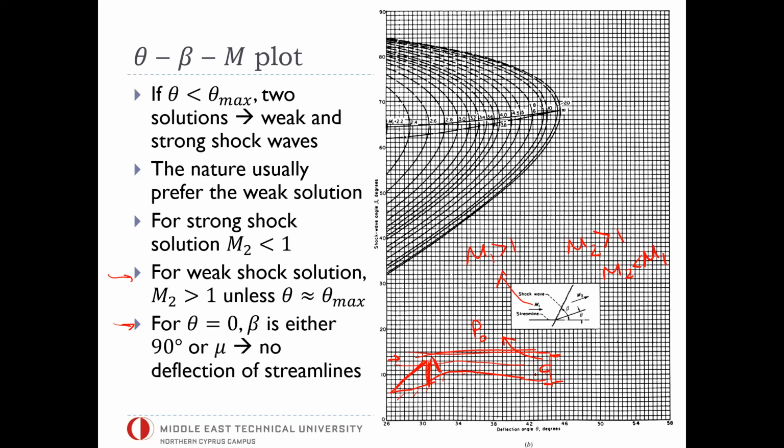So this inlet stagnation pressure is an important parameter in terms of engine performance as well. Therefore, we make use of the fact that we can generate many weak shocks, a train or series of weak shocks, and then maybe one relatively weaker normal shock wave, and then decelerate the flow.